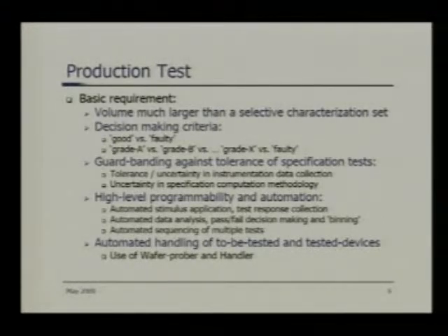For example, say Intel processors, there are speed grades, right? Some processors are not meeting say 3.2 gigahertz, it's probably meeting say 2.4 gigahertz. So they are selling it at a reduced price at a lower performance grade. Okay. So that concept comes from performance grading by binning.